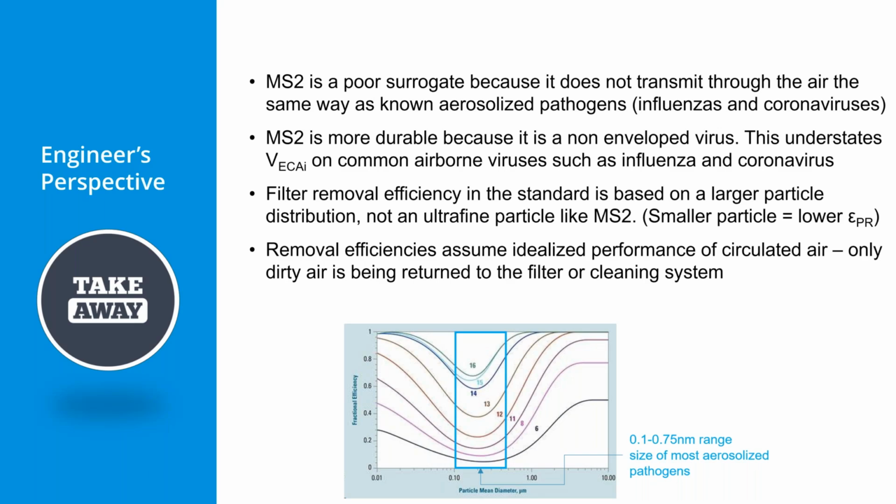But now, if you skip into the filter side, they are using a particle that's 3 times the size of MS2. So you get more effectiveness on the filter than you would really get if you were actually doing real viruses. And so the filter actually gets more credit than what would really be seen when you think about what you're trying to design around, which is these ultrafine particles, be they viruses or others that are transmittable through aerosolized inhalation.